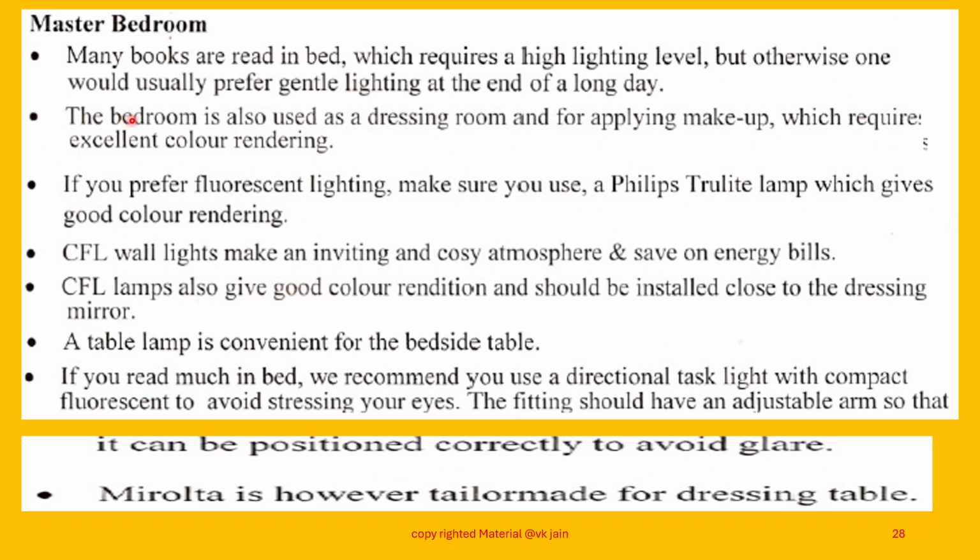The bedroom is also used as a dressing room and for applying makeup, which require excellent color rendering. If you prefer fluorescent lighting, make sure you use a Philips True Light lamp, which gives good color rendering over 0.9.